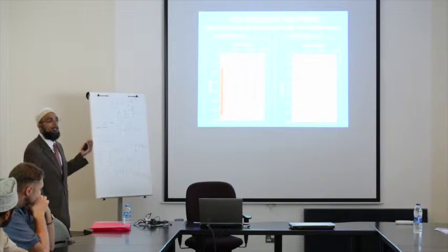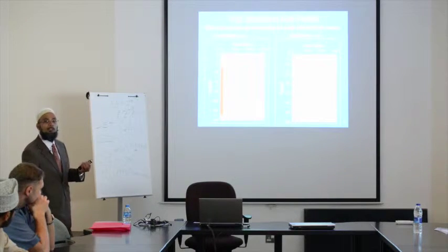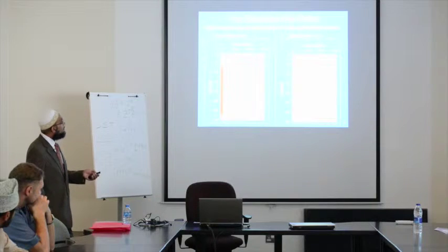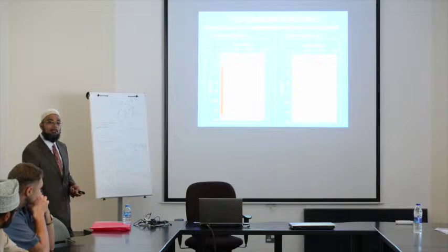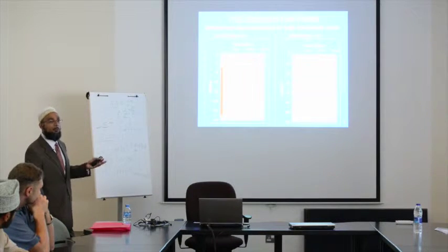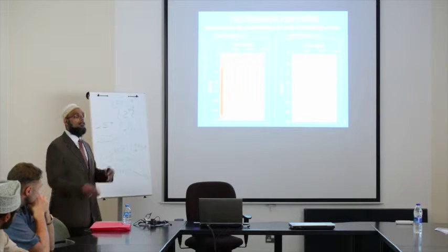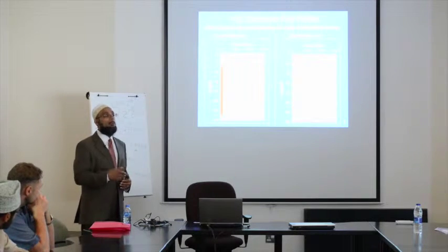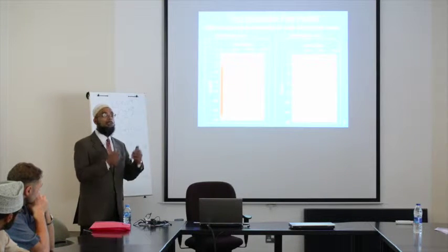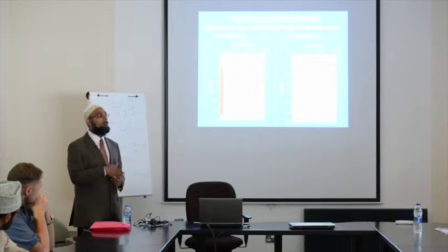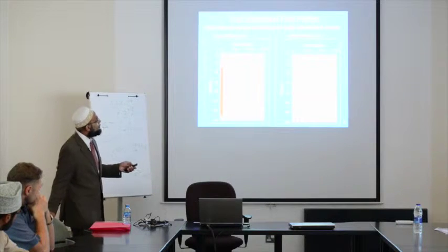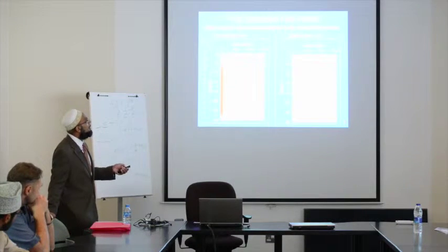Now, which one is a more difficult treatment to design? This one over here, right? Because here we are injecting acid where it does not want to go. We want the acid to go to the tighter zone, but it wants to go to the high perm zone. So here, this is almost a no-brainer. Dump acid, it's going to find the first zone, go there, high perm, and it will stimulate it. You measure the skin, the overall skin looks fantastic, and you move to the next well, right?